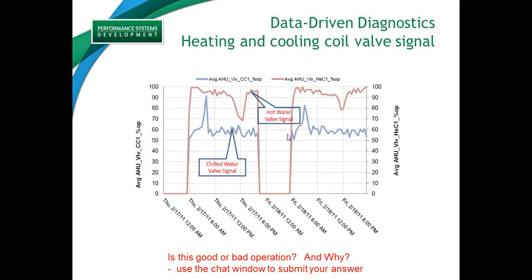But so this is the kind of stuff you're going to see in the energy charting metrics. The eCam tool will help plot these things to make it very much easier to understand what issues are going on. It's not going to jump right out and say, here's the problem. But the retuning process that we go through, there's a very specific set of sequences and a bunch of typical things and issues to look for and how to look for them for each one of the major building components.